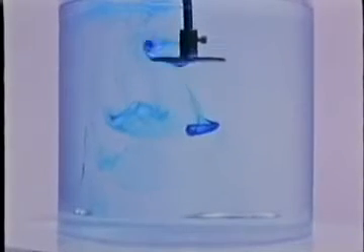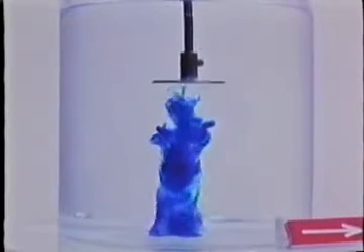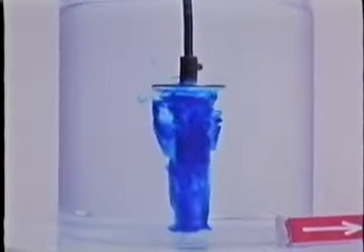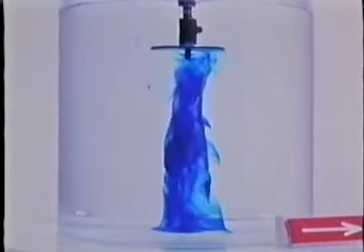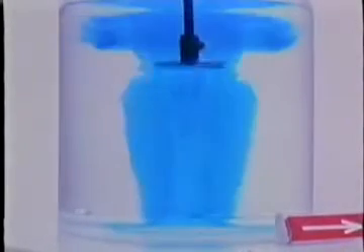We can study these inertia modes by exciting them with a small generating disk at the proper frequency. First, when the fluid is not rotating, oscillation of the plunger produces a disorganized flow of vortex rings shed from one side of the disk to the other. But with rotation and excitation at the proper resonant frequency ratio of 1 1/4, we produce an internal inertia wave mode with a nodal plane at mid-depth. Such oscillations with frequencies near the so-called inertia frequency 2 omega are common in the oceans and large lakes.